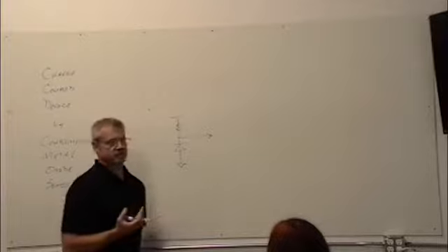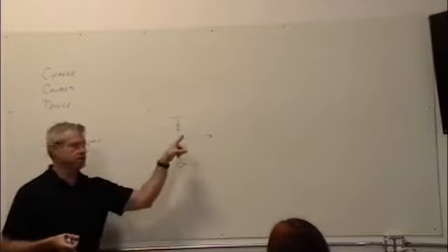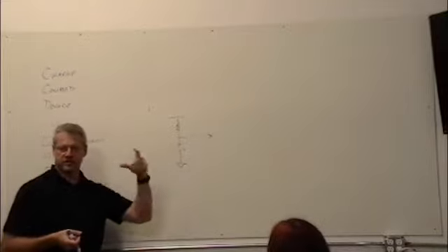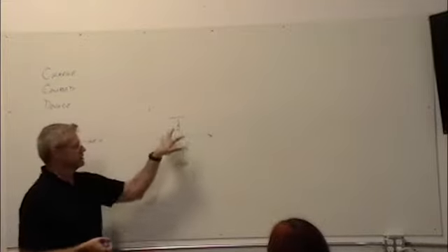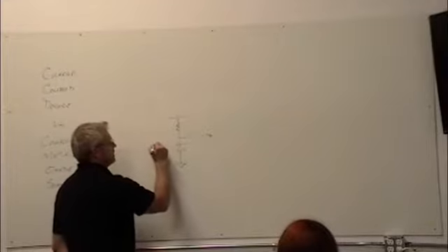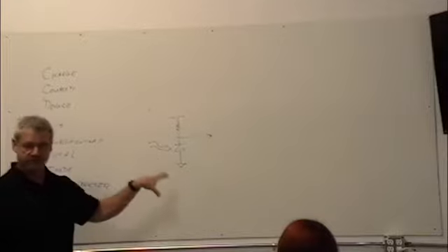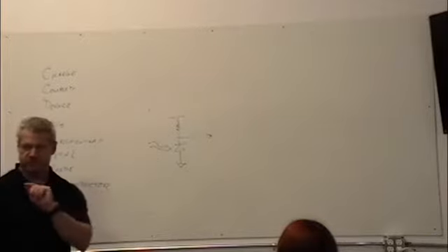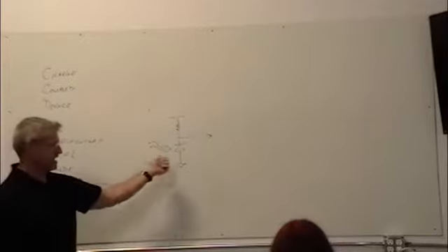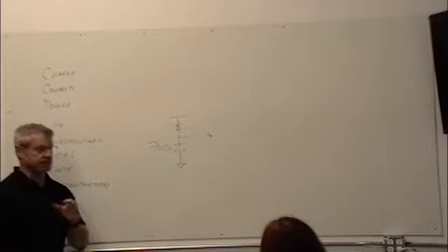So remember we talked about transistors and using a collector, a resistor and a collector path to be a load. So if we call this our load, and I have light coming in, this is an LED will do this, any diode will do this. LEDs are tuned to a specific color, and it's the reverse action, but they'll be especially sensitive to the color that they emit, generally speaking.